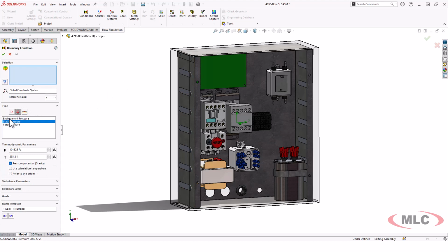I do not recommend using environment pressure. Why don't I recommend it? Because it does some weird things. It's static pressure in one direction, total pressure in the other. Meaning coming and going, you're going to get different pressure values, and it's not going to match up to what you expect. So if there's not significant pressures caused by moving volume, moving air, I always use static pressure.